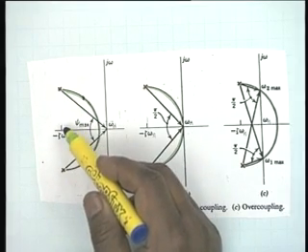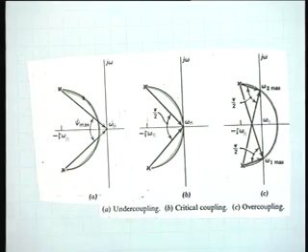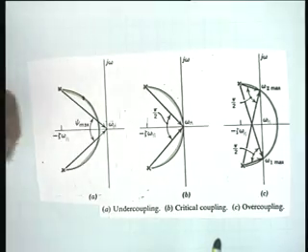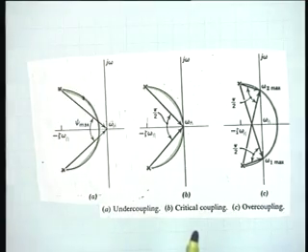k omega n by 2 is less than zeta omega n, so k is less than 2 zeta. Okay, no more damping. We are assuming that damping is small because we have got complex conjugate pairs of poles. This discussion is all based on the assumption that there are complex conjugate poles. So we take damping away from our consideration. We now only depend on k. Why? You saw the magnitude has been expressed now as sine psi divided by 2 times 1 minus k squared. So zeta has been dropped out of the picture.